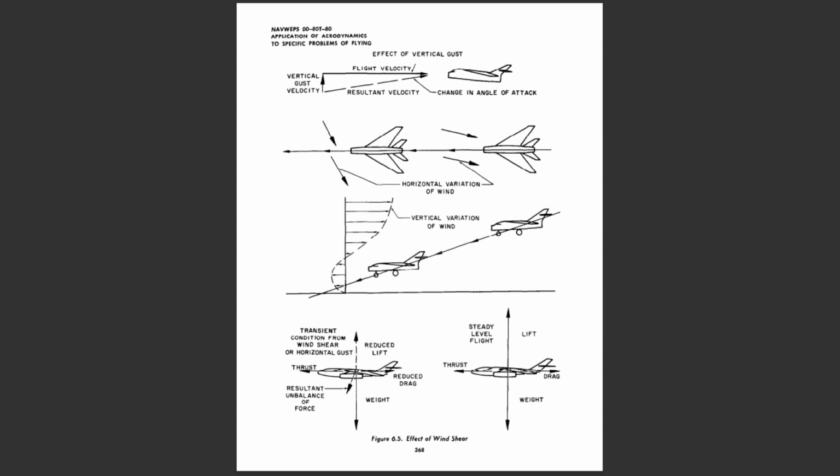structural damage. At low flight speeds during approach, landing, and takeoff, the effect of the vertical gust is due to the same mechanism of the change in angle of attack. However, at these low flight speeds, the problem is one of possible incipient stalling and sinking rather than overstress. When the airplane is at high angle of attack, a further increase in angle of attack due to a gust may exceed the critical angle of attack and cause an incipient stalling of the airplane. Also, a decrease in angle of attack due to a gust will cause a loss of lift and allow the airplane to sink. For this reason, any deficiency of airspeed will be quite critical when operating in gusty conditions.